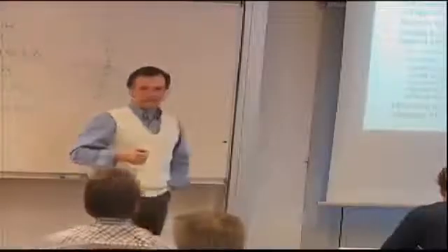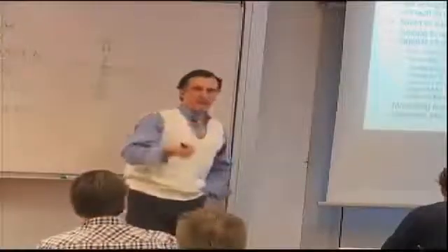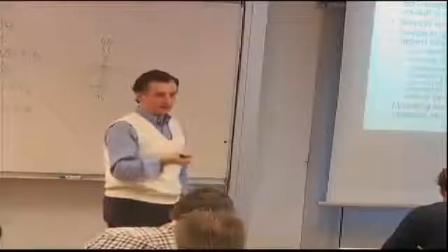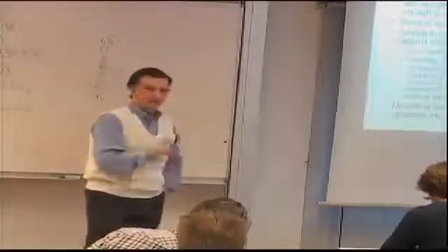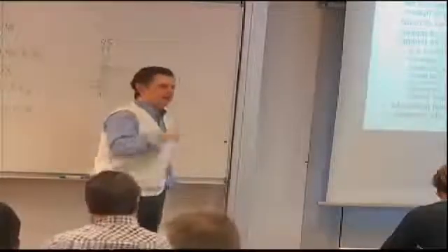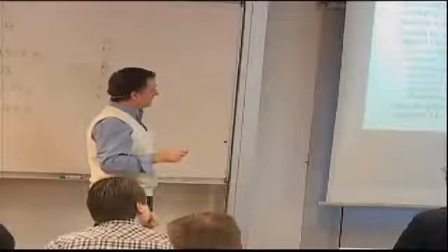Even if I could determine stresses and strains accurately, that's not even half the battle. I need to have a way to combine those in a failure criterion or something that tells me whether the structure fails and in what way it fails. And as I've already been mentioning, strength is only one of the many possibilities. In fact, some form of stability, local buckling or global buckling, will be most of the time the critical one. So you need to design, therefore, knowing what your specific failure modes are going to be.